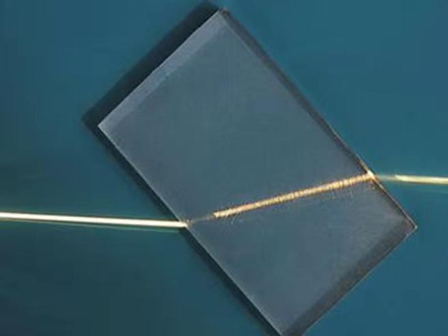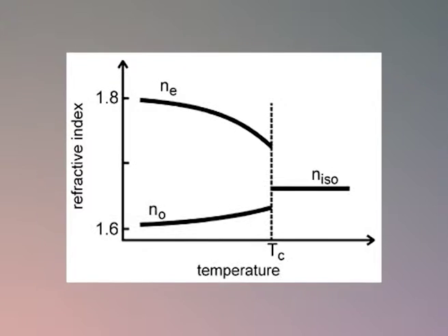Temperature affects the density. Density further affects the velocity of the light beam as it passes through the sample. And the refractive index is proportional to 1 by T, that means it is inversely proportional to temperature and also inversely proportional to the wavelength. Thus, refractive index gives an indication of the composition and the thermal history of glass.